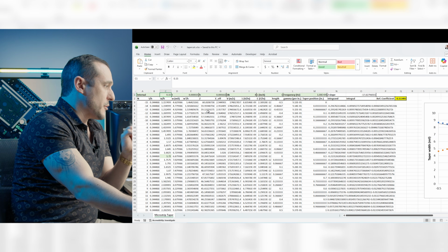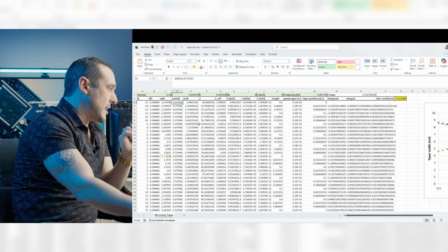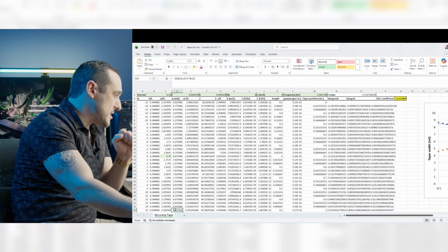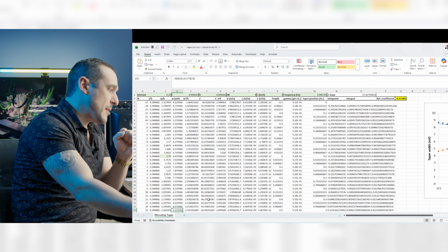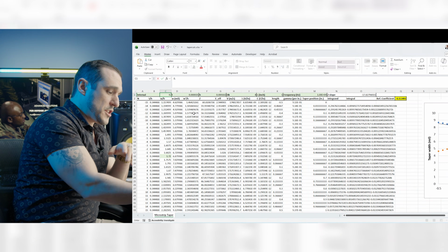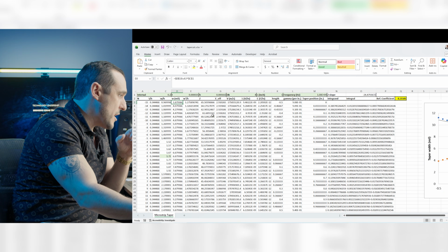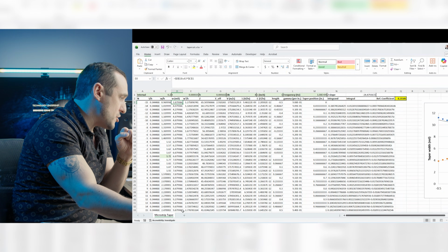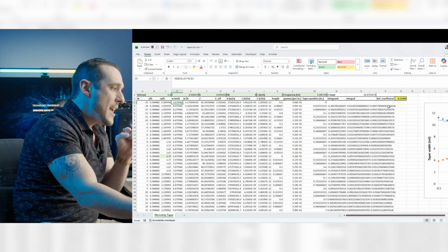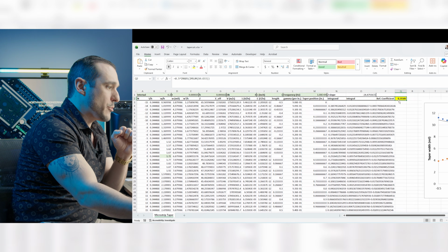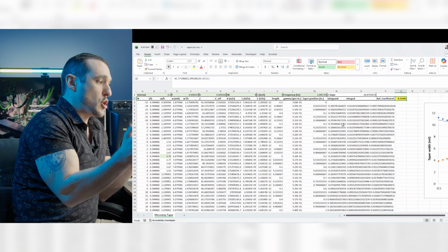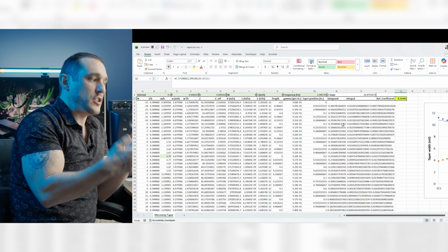So by setting an interval value of 0.15, that allows us to vary the width from 4.6 mil all the way up to 9.13 mil. Now if I change this interval value to 0.2, you can see here it changes our width from 3.88 to about 9.88, and you can see here that it calculates the reflection coefficient for this taper. So we would expect a reflection coefficient coming into this taper of only 20%.